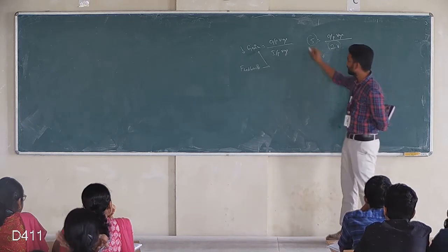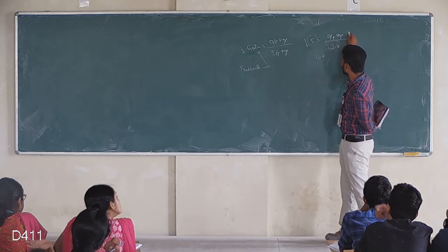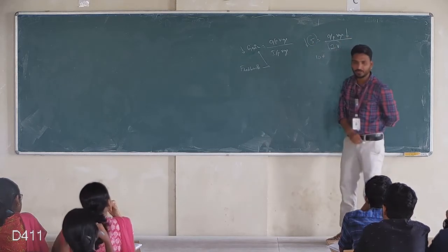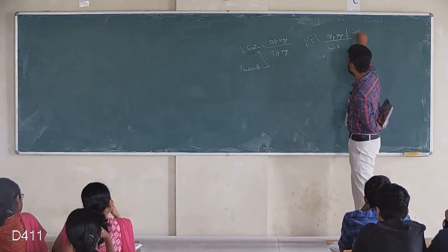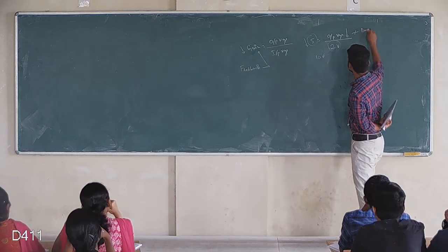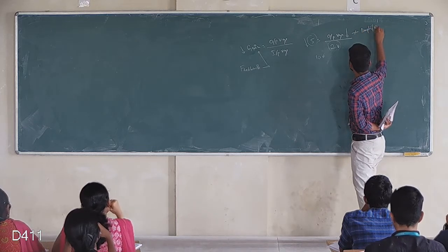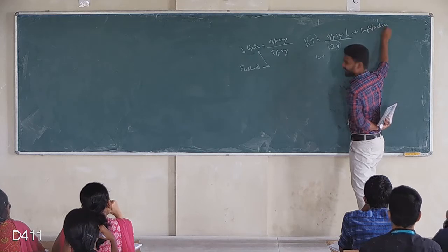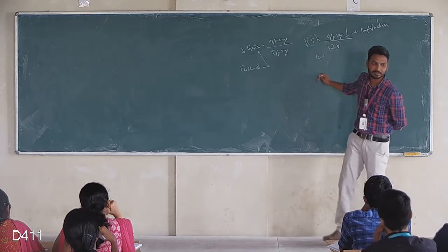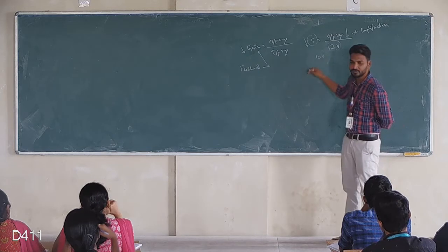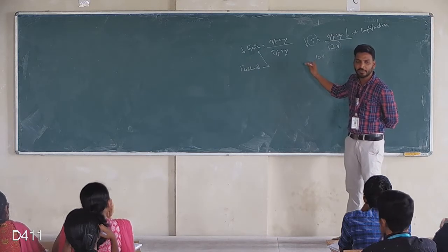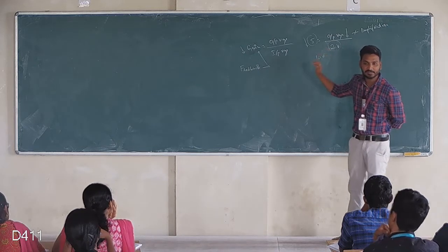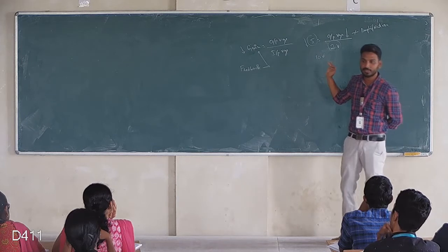So automatically, when gain is reduced, the output voltage will also reduce, which affects the amplification. Amplification should always be high, but in this case due to feedback the gain gets reduced. Gain gets reduced means automatically output will be reduced. That is the drawback of collector based bias circuits.